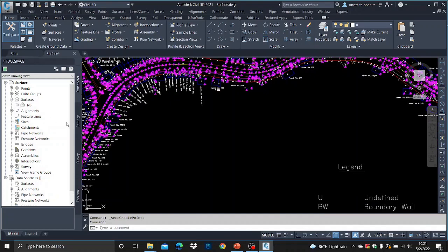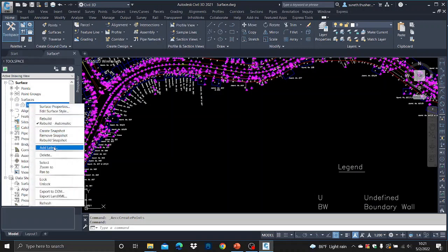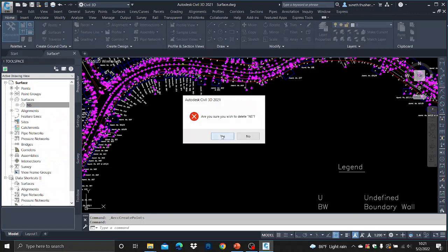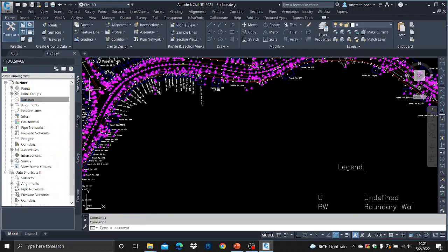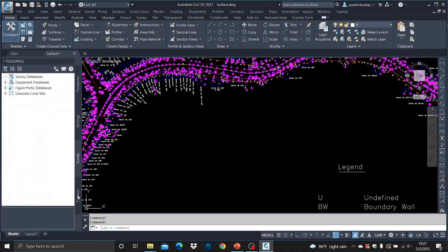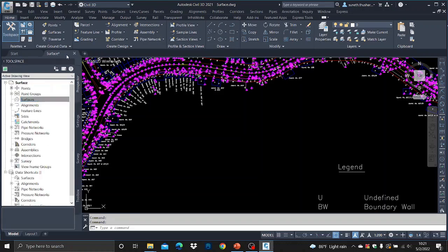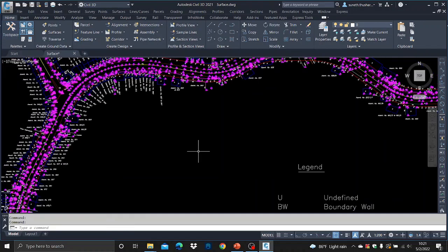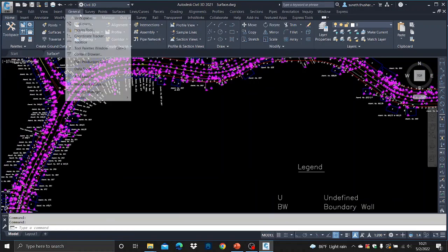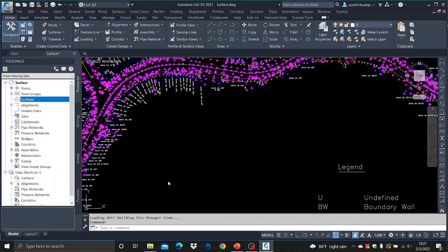You go to the surfaces. There is some default one. You can delete it. Right click, delete. Now if you have just press some settings or survey or toolbox, this is not there. Please remember that this should be prospector. If this is gone, you can always have it by general tool space, right? And the highlighted one should be prospector. Then you go to surfaces, right click,